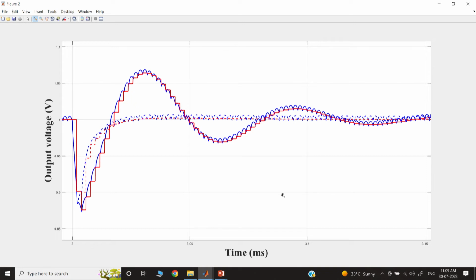Because in stable pole-zero cancellation we are trying to shape the loop, but if you recall the output impedance expression, it is the open loop output impedance divided by 1 plus the loop transfer function. So, whatever loop you shape, in the numerator you still have the open loop output impedance, and that creates a problem. So, there is an alternative way to shape the output impedance, and that we have discussed in lecture number 36 in our earlier NPTEL course, the control and tuning method.